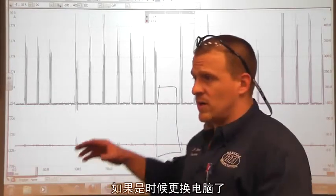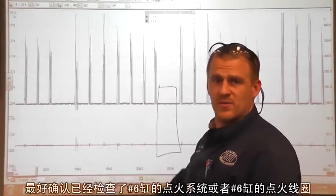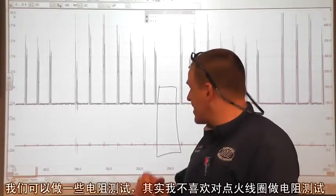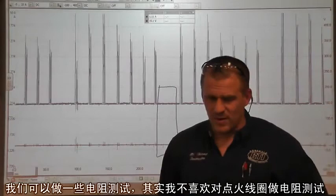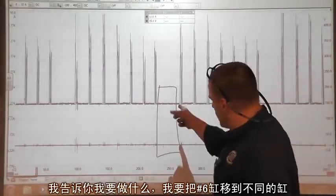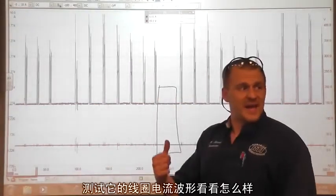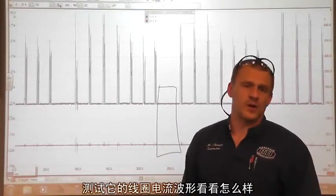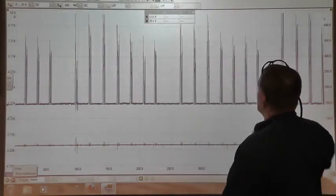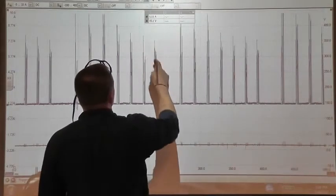So when it comes time to, let's say, replacing this computer, you can be sure that we better be doing some checks on this cylinder number 6 ignition system, or this cylinder number 6 ignition coil. We can do some ohm tests on it. I don't really like the ohm meter for ignition coils, and I'll tell you what I want to do with this: I want to move this cylinder 6 to a different cylinder, one that's functioning right now, and take a coil current ramp pattern of it and see what it looks like. And that's where some of this theory is going to come into play. We'll see where this is going to take us, but if we have to do that, we will.